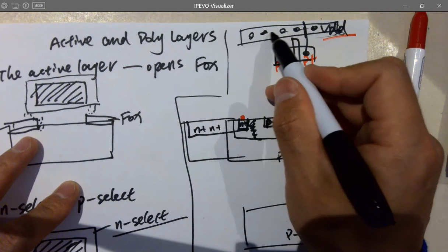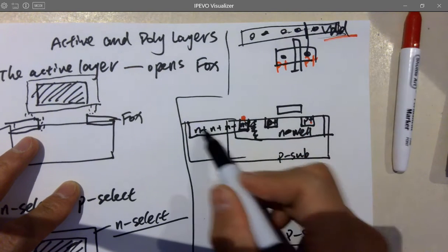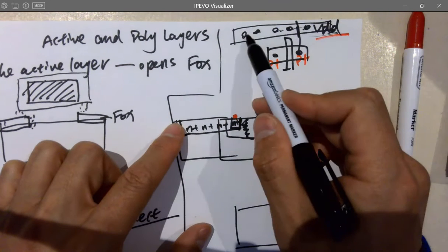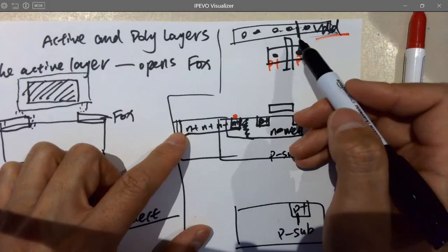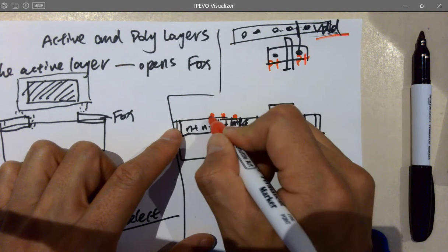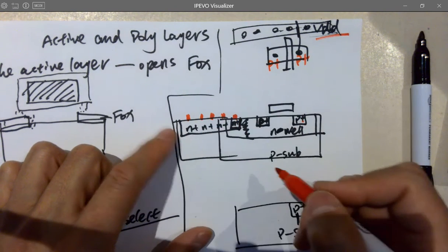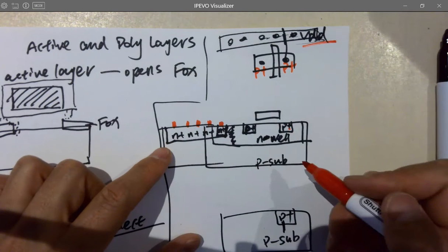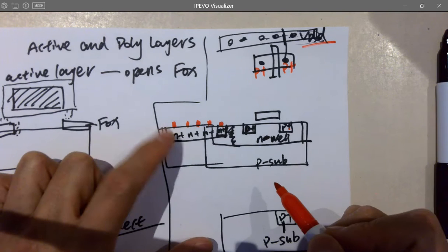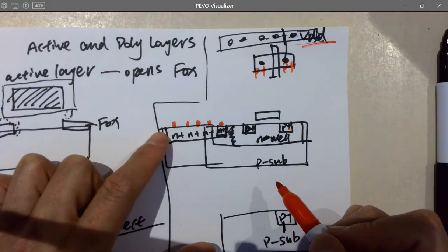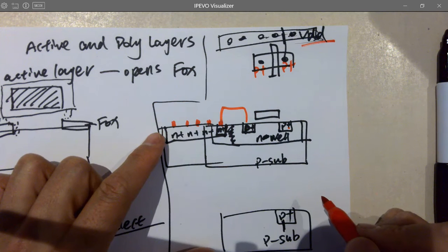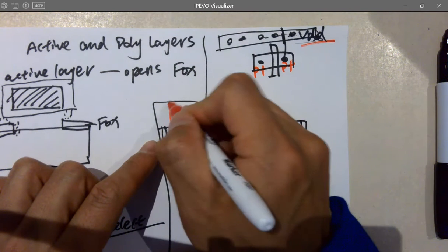So what are these vias? It's one piece. It's not separate ones. I'm just labeling that. So what about these ones? They're just different vias. So you have a long wire that has multiple vias on the top, right? And then you make a connection from P plus to the N act. And then you short this to VDD.